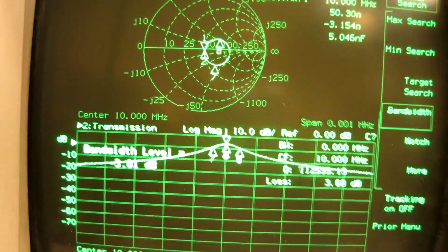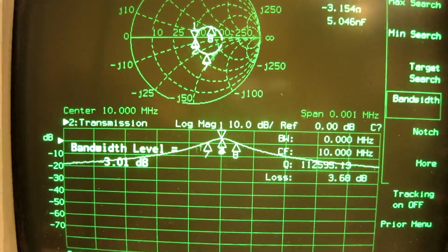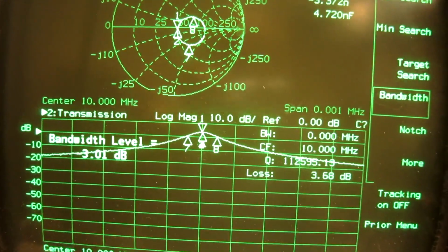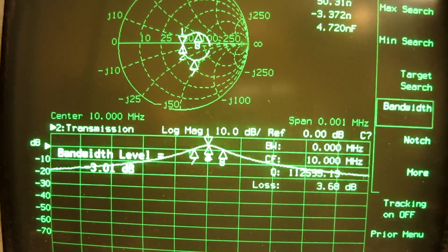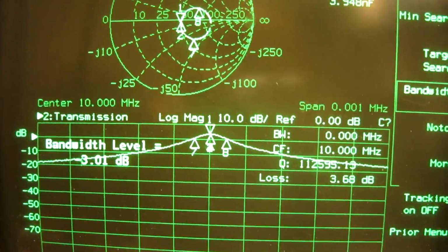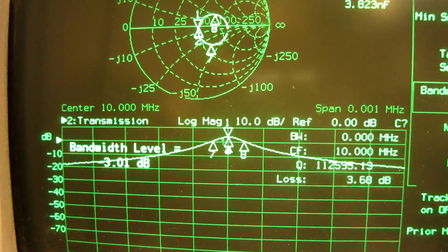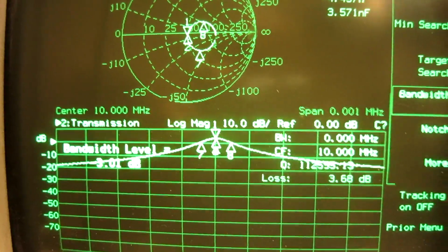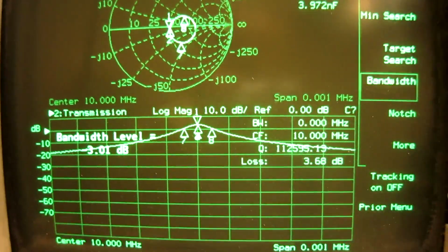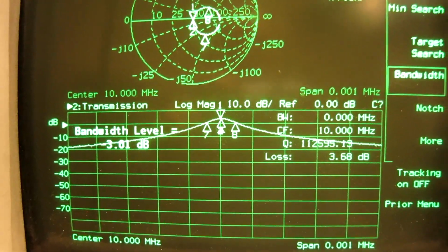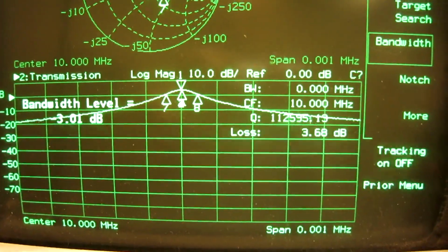I have connected the power amplifier and I'm now looking from the input connector through the filter and the first amplifier and through the power amplifier to the limiting output. But the level is far below where clipping occurs, so I see a gain of 3.7 decibels.